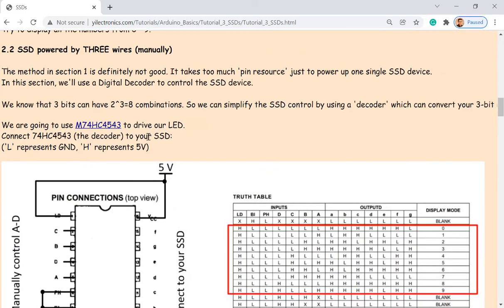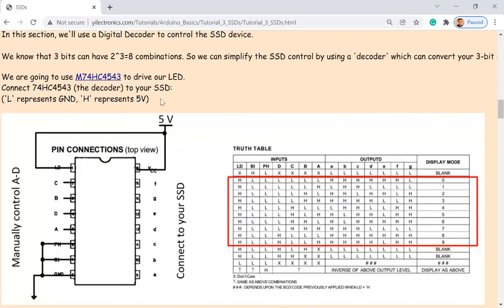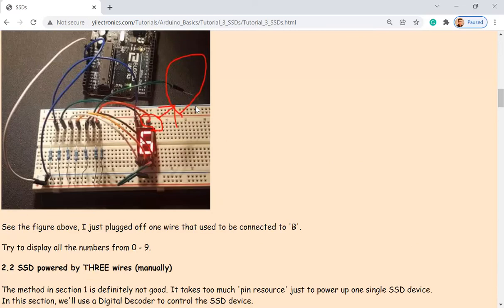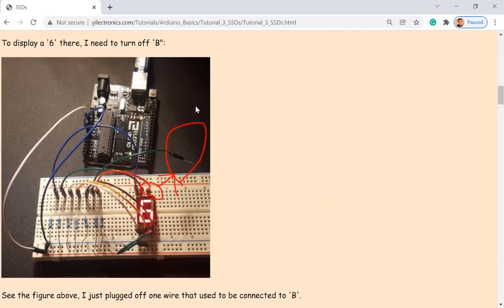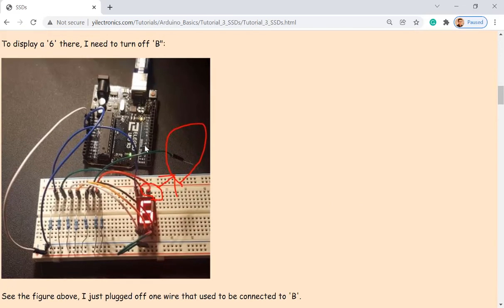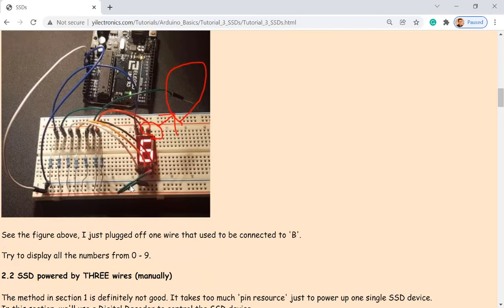So you have 2 different ICs. There might be more than 2 ICs in your box, but definitely you want to read the print on the top to make sure you are using the correct IC. So the decoder is 4543 in a box, and that decoder is being used to reduce the number of pins being used from the Arduino board. Why does it work?